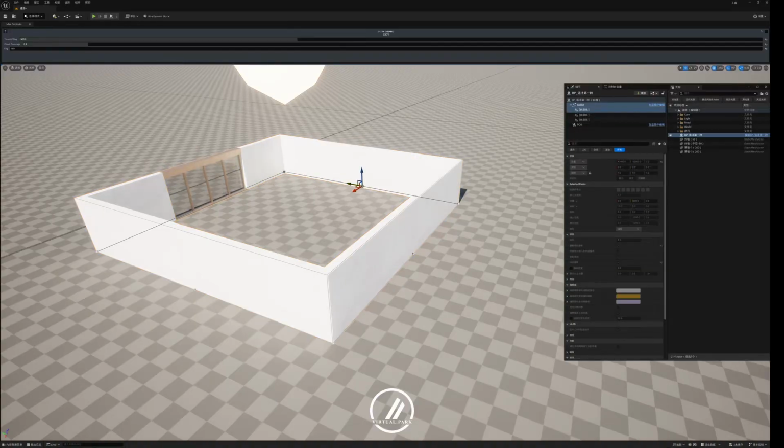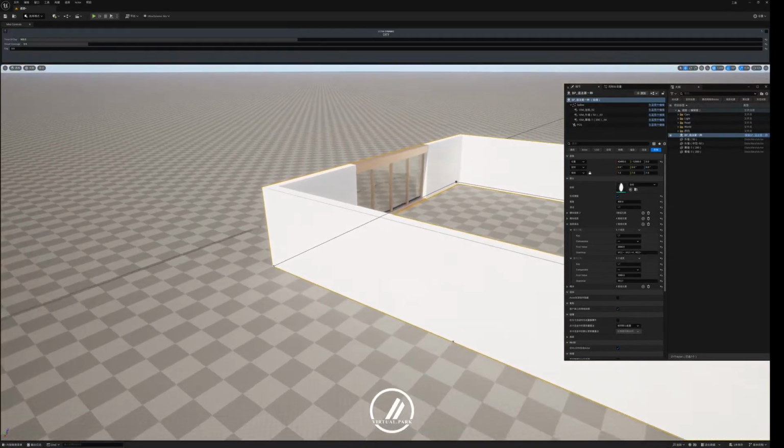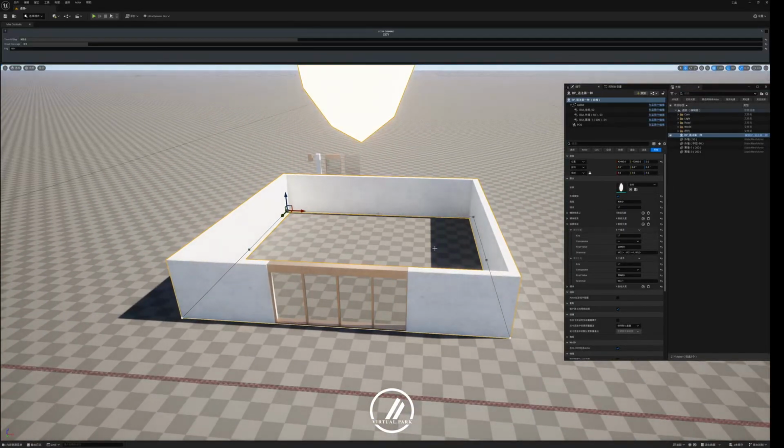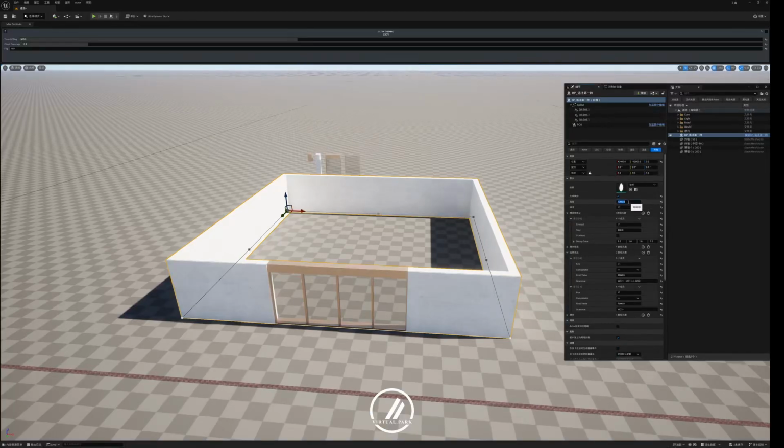Following the above logic, many complex shapes can be generated. Due to time constraints, I'll only demonstrate a simple square-shaped wall here. I'm going to change the floor height to 3 stories. Then, I'll write the rules for the second floor. All the syntax should be separated by commas.